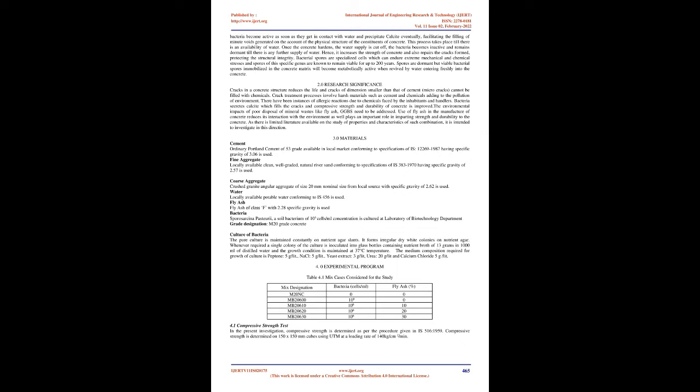To minimize crack width, extra reinforcement should be provided or the crack has to be treated. Providing extra reinforcement means an increase in steel quantity, in turn an increase in the cost of the project. The second option is treatment of cracks. Cracks can be treated by using chemicals, which is again a costly and tedious process. Reaching the deeper portions of the cracks which are away from the surface, in a structural element, is very hard and sometimes it is not possible.